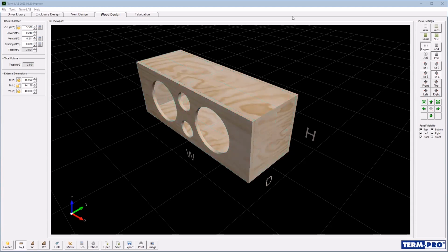If you have 4 woofers or 8 woofers or whatever, the front loading is different for each sub. But if you had individually chambered woofers and all of those chambers were identical, the back load for each driver would be the same, but the front load varies from chamber to chamber. And in my experience, I've seen phase problems when you do that. One way to address that is if you use a common rear chamber, then the loading on the back side of the cones is the same as on the front side. And so those little variations tend to negate each other.